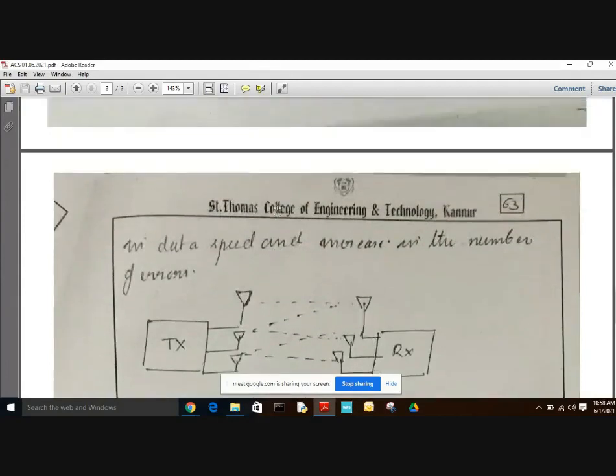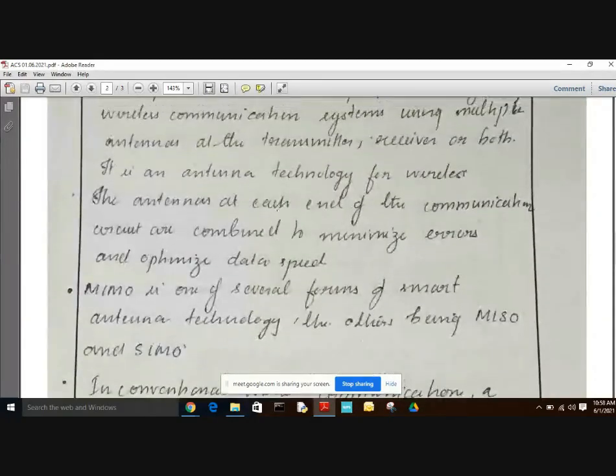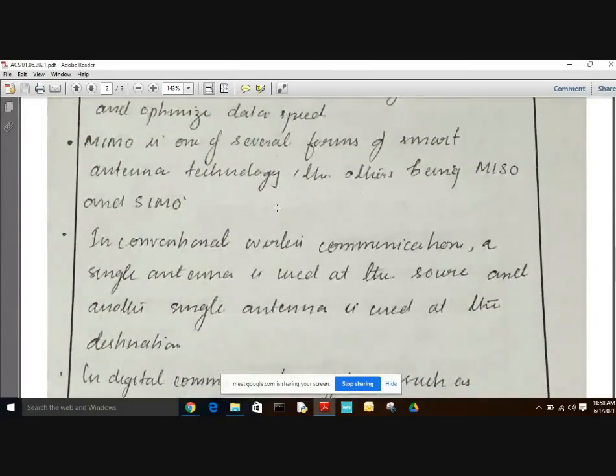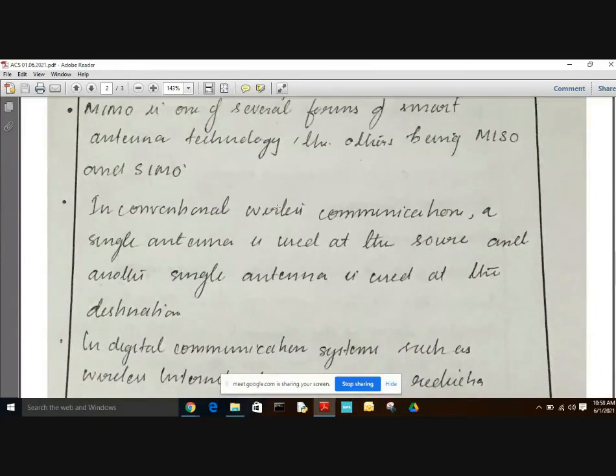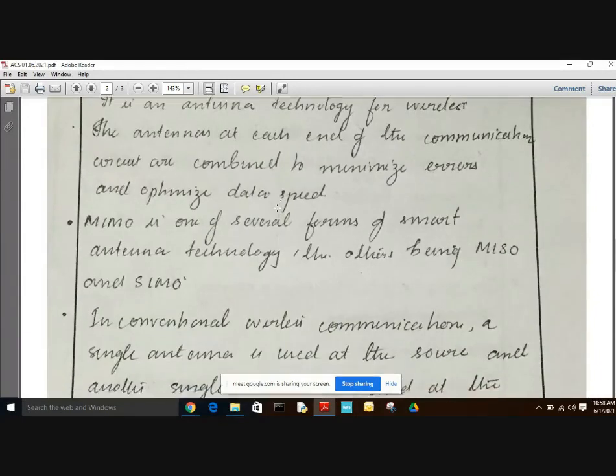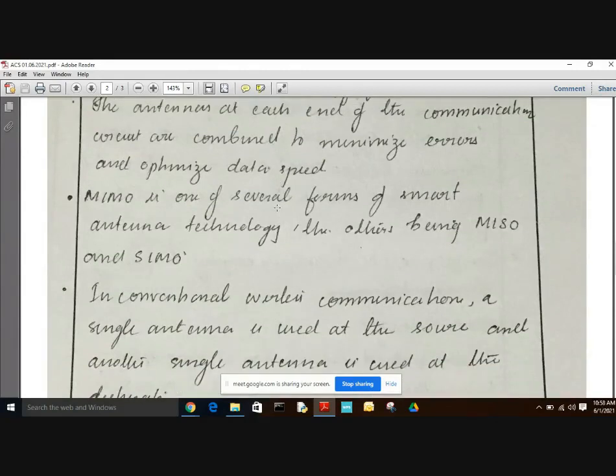This is used to enhance the performance of the wireless communication system by introducing multiple antennas, multiple input and multiple output. By introducing this MIMO system, it increases the coverage, position estimation can also be increased, and it has good coherence. The effect of fading can be reduced as the receiver can select one propagation path with a good signal, and there will be no break of voice in calls in this MIMO system.